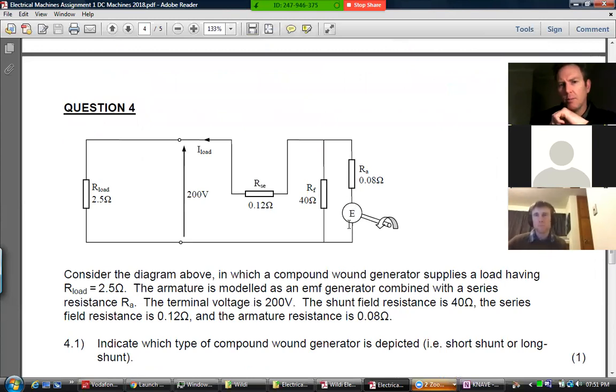Okay, so for example, the generator, if you want 200 volts here, you've got to work quite hard to get it. Let's say it's 220 volts over there, so that you can afford to drop maybe 10 volts across this thing because of current getting sucked through here. That maybe gives you, let's say, 210 over here. Then you've got to afford to lose another 10 or something through this because current's getting sucked through there because of the load. So that eventually you end up with 200. So the back EMF always ends up significantly higher than this voltage. And then there's two steps of loss. One is through this guy, and the other is through that fella there.